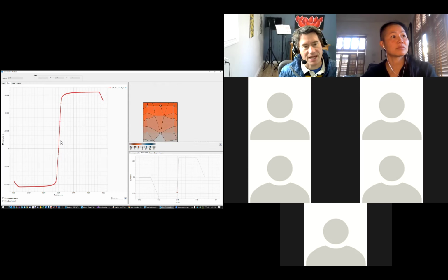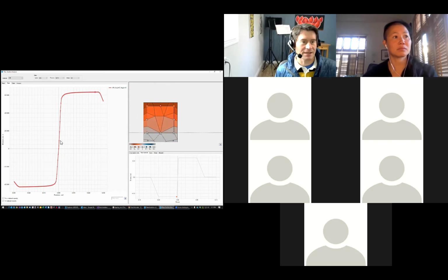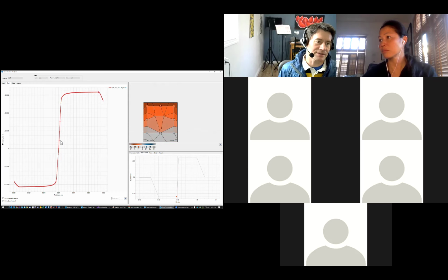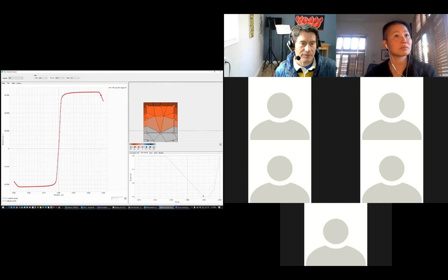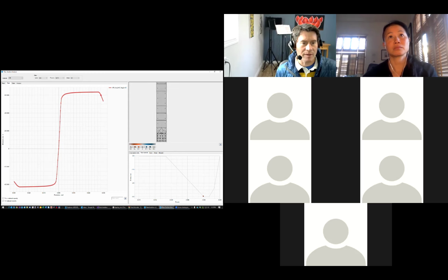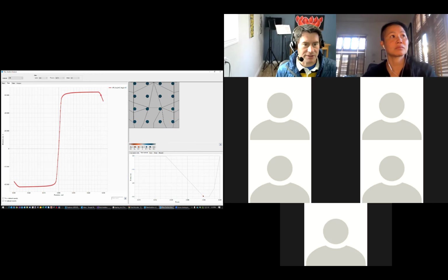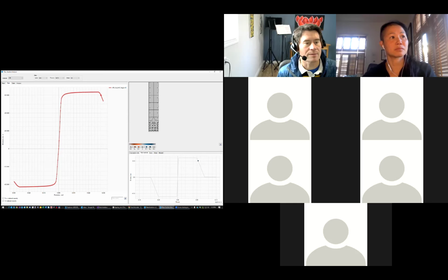And I can see what's happening as my rebar eventually gets up to near the yield strain, and it sticks right there, and then ultimately we get some strength loss. And I wonder what's happening there. I think it's probably this. The cover is starting to break off there. Maybe I'm getting some rebar fracture on the back end. Yes, so I'm starting to lose strength in the rebar on the back end.